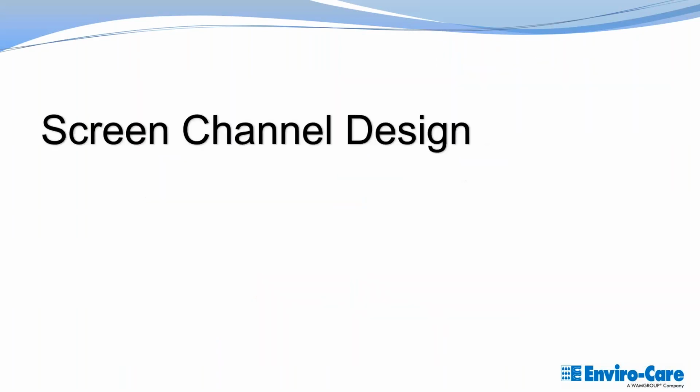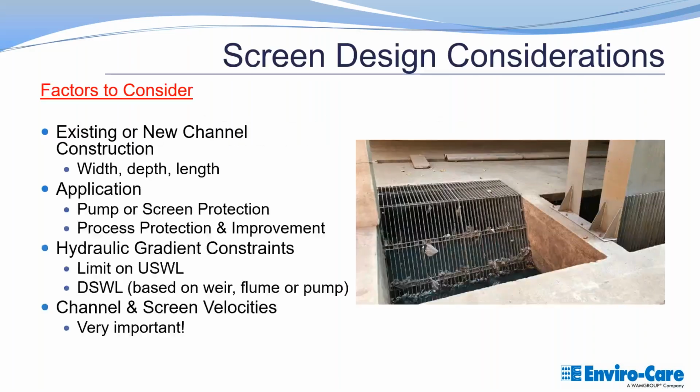Now, screen channel design. You can take the best screen, put it into a poorly designed channel, and you'll end up with either a flooded channel or a lot of material getting downstream. So we need to make sure that we consider all the factors that go into screen design when we're looking at it. First is going to be the channel construction. Is there a certain width, depth, or length we need to constrain in, especially if it's existing? A retrofit can be much more challenging than a new channel construction where you can tweak it a little bit.